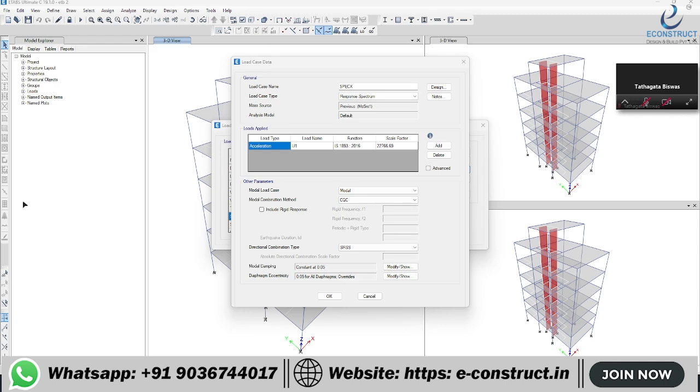So this non-orthogonal case is generally threatening for the mid-rise structure, where the G plus maybe 20, 25 maximum. If it is beyond 30, it's wind which is going to govern. Are you getting?